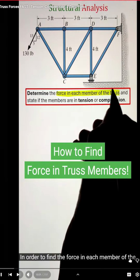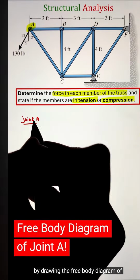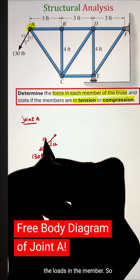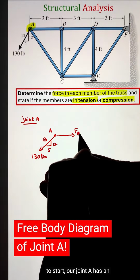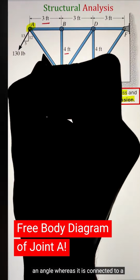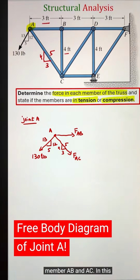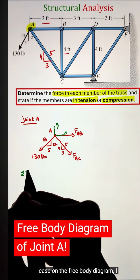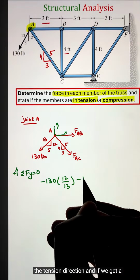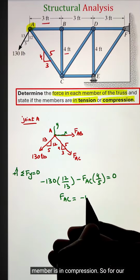In order to find the force in each member of the truss, we can utilize the method of joints by drawing the free body diagram of each one of them and identifying the loads in the members. To start, our joint A has an external load of 130 pounds that is applied at an angle, and it is connected to members AB and AC. On the free body diagram, I always draw the forces in the tension direction, and if we get a negative number, that means the member is in compression.